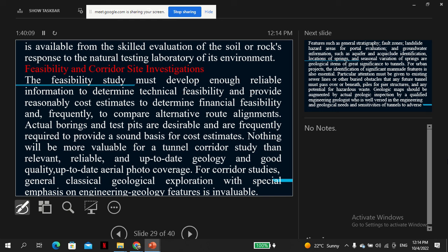So of course, you guys are in fifth year. This is a second year. So you did your technical engineering and you did geophysical methods: the ground penetrating radar, the MASW, those things you did. So these indirect methods can complement. But please note, these geophysical methods may not replace the actual pits. They can help you interpret the data. They can supplement, but cannot replace the fact that you actually need to do a pit.